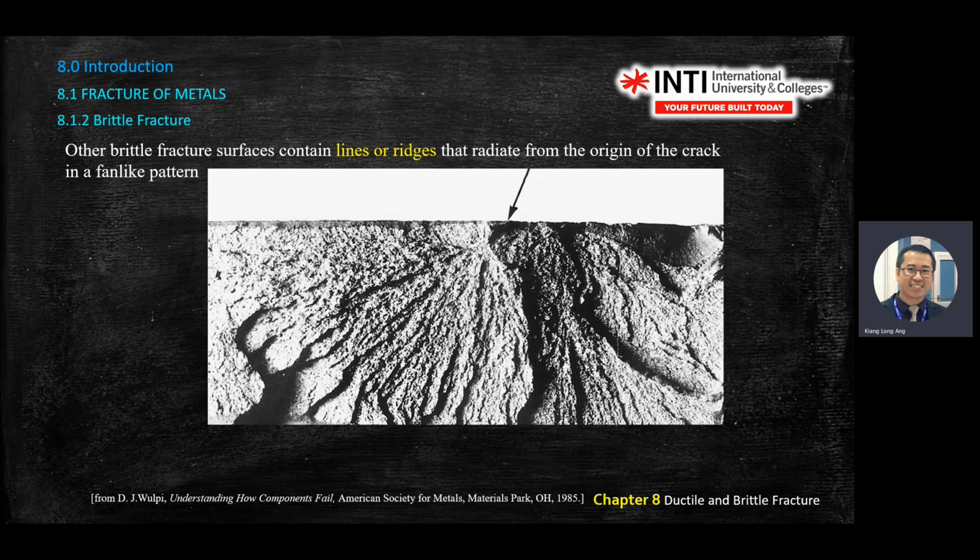And how do you know the direction or origin of the brittle fracture? You see the lines, wrinkles, especially in this diagram. You see there's a line of rays here. They must start from somewhere. So if you see this diagram, it will be in this section. We don't know the exact place, but it's from this direction, and then it starts to go back down.